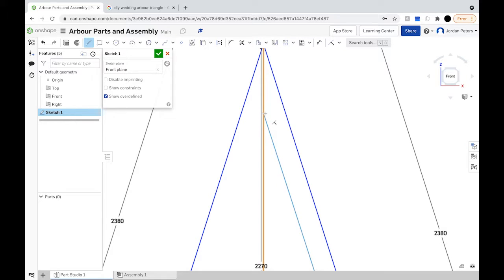So if we take it to this middle upright line, you can see that perpendicular symbol just came up, and the other symbol just means that we're connecting to the line. That means it's perpendicular to that 100mm line we drew down the bottom, which means that it's exactly 90 degrees to that line, and because the other line's also 90 degrees to it, it's exactly parallel to the other line. So it's exactly side by side, that line.